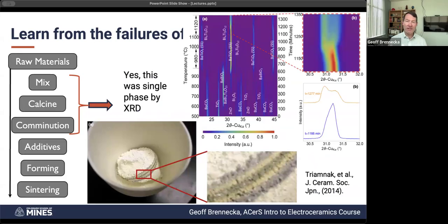And as an example of this, I will point to some work that I did a little over a decade ago, where according to all of the ex situ X-ray diffraction that we did, we mixed barium titanate plus bismuth zinc titanate. We were making these capacitors that were relatively stable with temperature and with electric field. But every time we would calcine these things, we would end up with this Oreo cookie looking layer within the powders. And we said, there is something wacky going on here. But we would throw these powders in the X-ray diffractometer at room temperature, and they always looked the same.